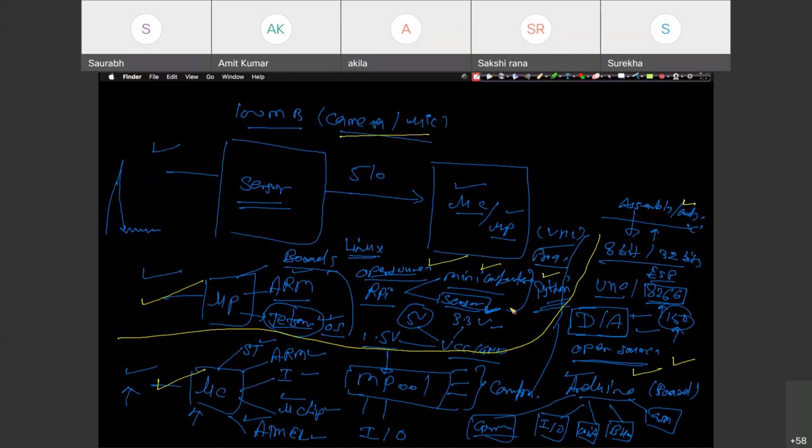One small limitation that you will find in Raspberry Pi is that there is no analog to digital conversion, there is no ADC. Which means if you have an analog sensor, if the sensor is analog in nature, you should not work with a microprocessor, I mean this Raspberry Pi. Okay. But even so, if you have an analog sensor and you want to work with Raspberry Pi, you should attach an Arduino with that, right? So let's take a case.